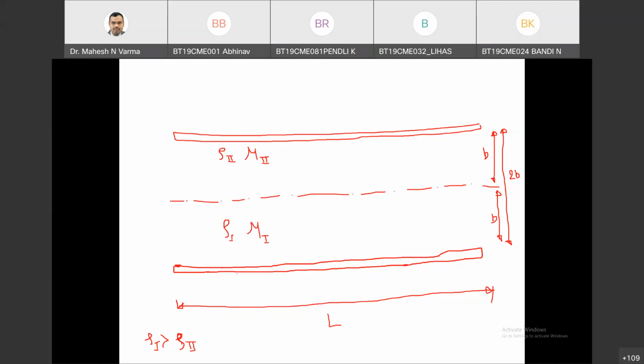So viscosity is an important property in momentum transfer that we have already seen. Viscosity is so important that phases are considered different for two fluids if they have different viscosity. If two fluids have the same viscosity, even if they are immiscible with different density, they can be treated as a single phase and the problem can be solved. Hence, we can take the origin at the center.